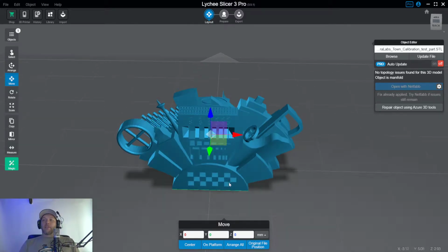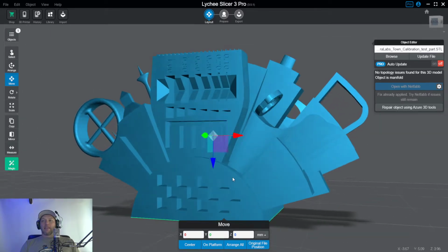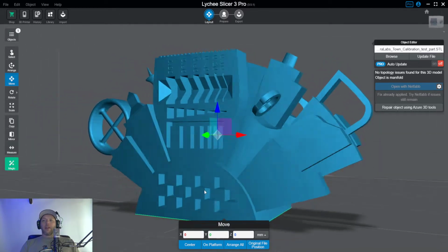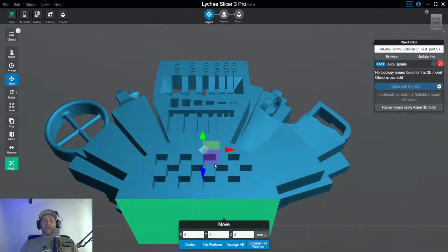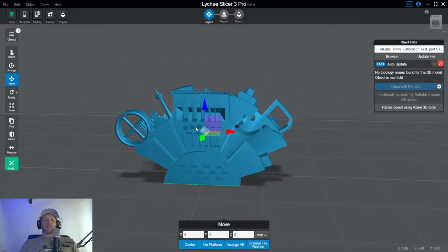So yeah, the checkerboard, as mentioned in chat, is a pretty good indicator. If it fills up with resin, you get pooling in there. There's a lot of variables that can affect exposure immensely. One thing that a lot of people never realize until later, or until they catch somebody who happens to know, is temperature. Temperature, and I can't stress this enough, temperature is so important when it comes to exposure settings.